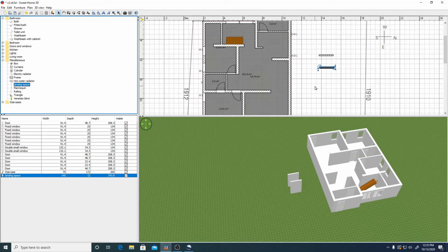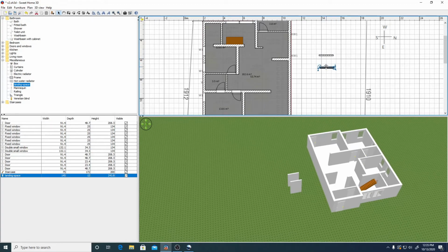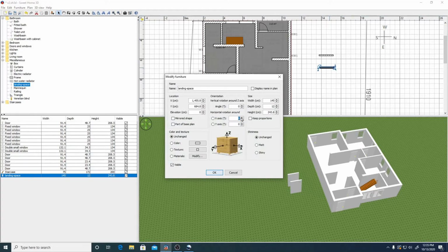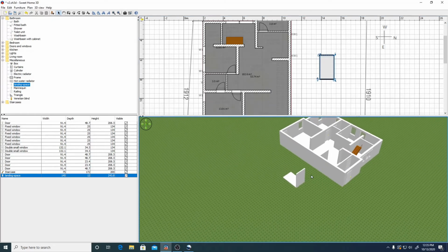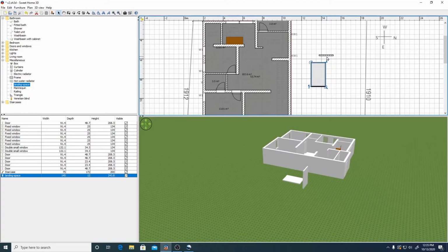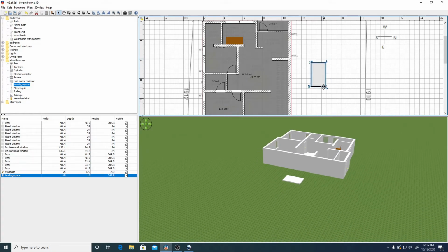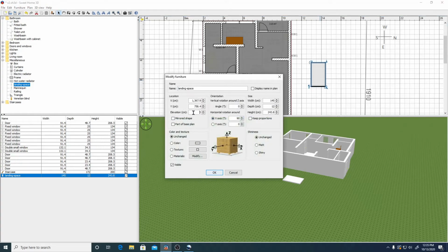So now if you look at, here is the difference. The one we exported is just a wall. Now the other one you imported, you can drag, you can change the elevation. It's like a standard furniture category. So I'll just change the angle here so that it appears 90 degrees horizontal. Now if you look at, it's actually horizontal. Only thing is that it doesn't have an elevation now. So we don't need the original one. I'll just delete it. Now I can adjust my elevations, height, everything.